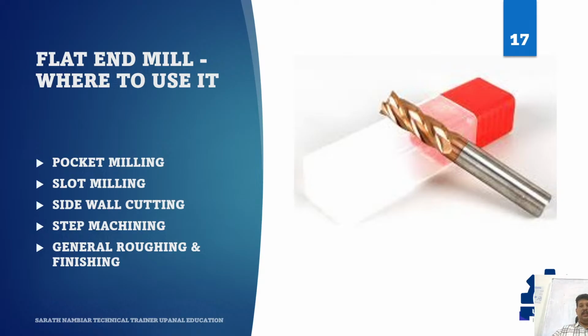The sharp corner edges of flat end mills take stress. During heavy cuts, vibration, poor holder clamping, or aggressive plunging, these corners may chip off. And once the corner chips, finish quality can reduce. That is why many shops shift to bull nose cutters for demanding jobs. But still, for everyday machining, flat end mills remain one of the strongest choices. And if you understand this tool deeply, you can solve many machining tasks confidently.